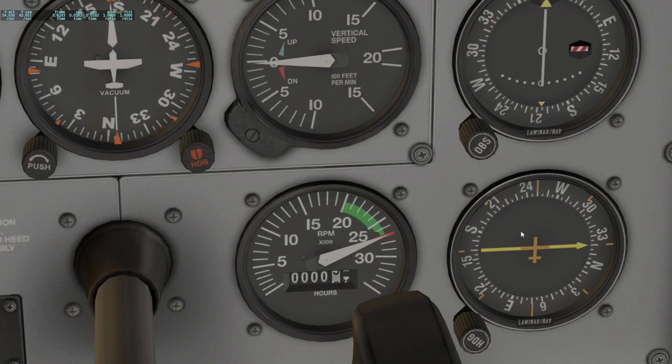We know the rules of 30 degrees, 60 degrees, and so forth. Okay, what is 30 degrees from 250? Here's 10, 20, 30. Here we go, 220. And another 30 degrees. Here we go, 190. So first thing I need to do is to fly parallel to this radial until I hit the 60-degree difference from that radial that's selected, which is right here, which would be the 190. So I need to fly in the direction 230.